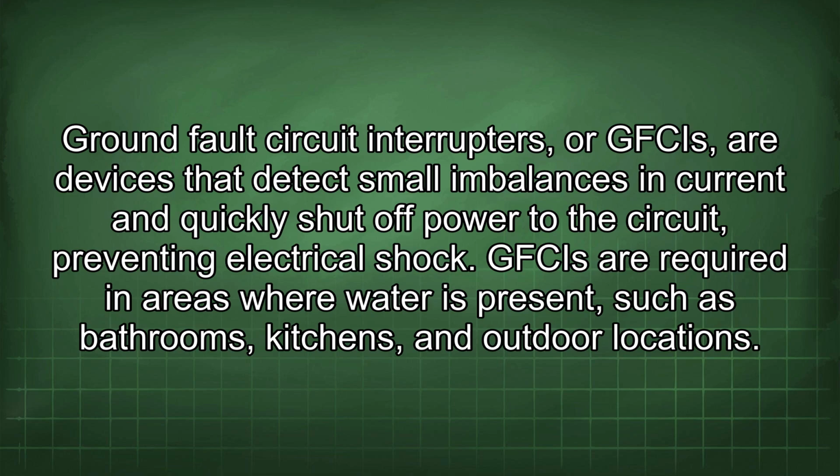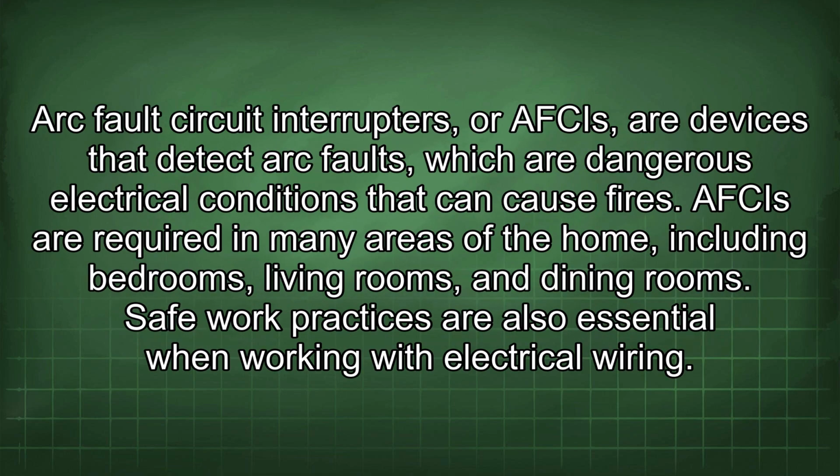GFCIs are required in areas where water is present, such as bathrooms, kitchens, and outdoor locations. Arc fault circuit interrupters, or AFCIs, are devices that detect arc faults, which are dangerous electrical conditions that can cause fires. AFCIs are required in many areas of the home, including bedrooms, living rooms, and dining rooms. Safe work practices are also essential when working with electrical wiring.